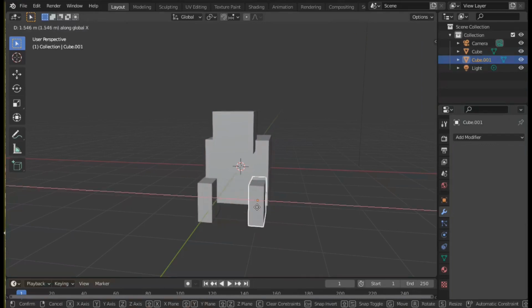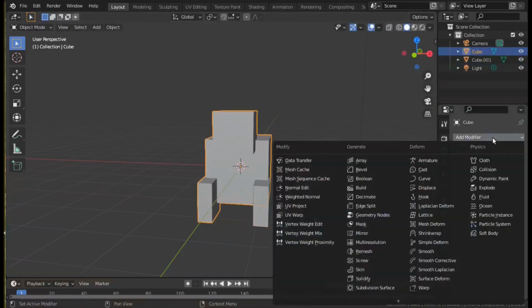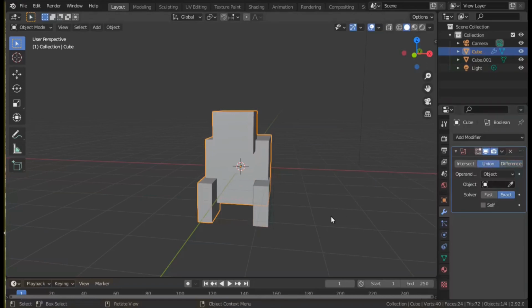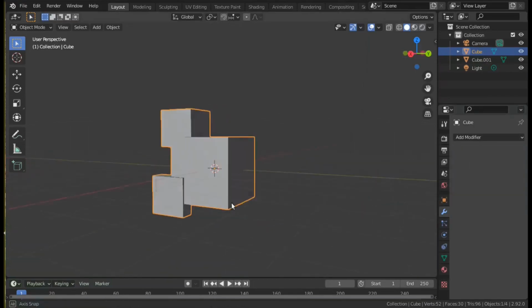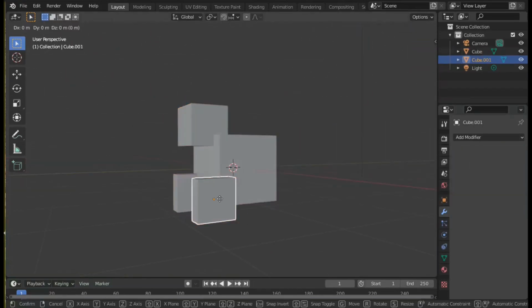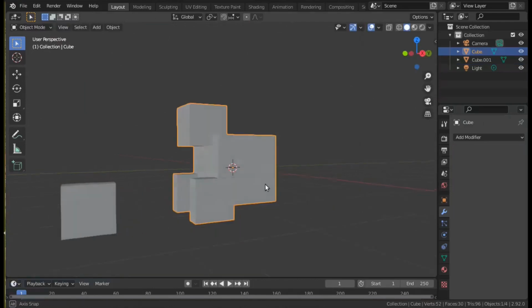And finally, after the last one, move the working modelling cube over to the side. Now, with this new shape, we're going to try adding a few more modifiers. The first one to look at is the subdivision, or the subdivision surface. And this allows you to subdivide by different levels.